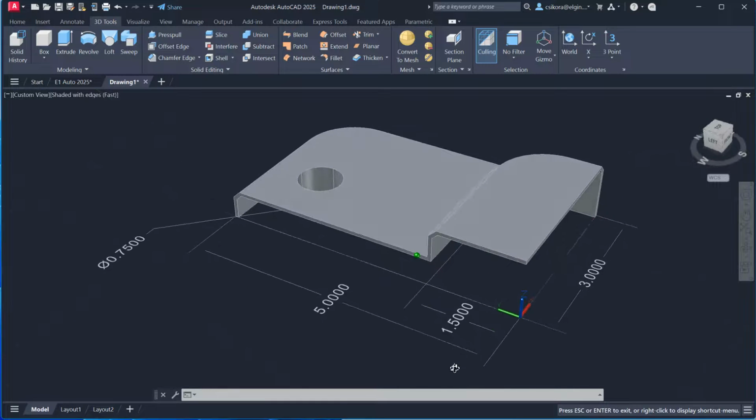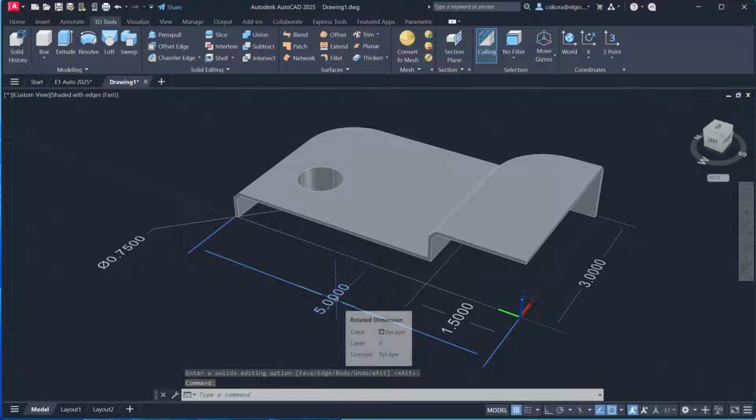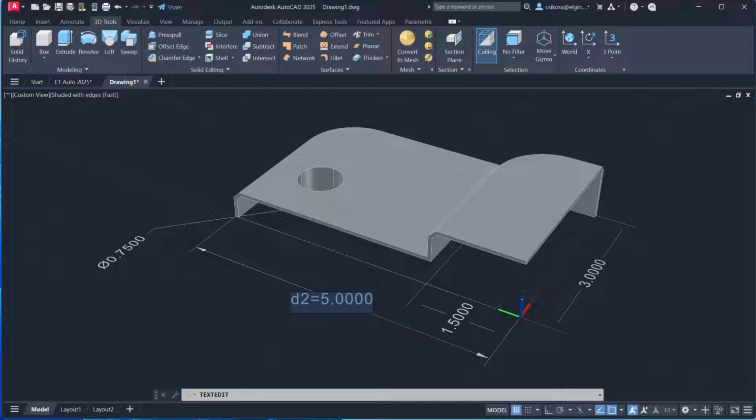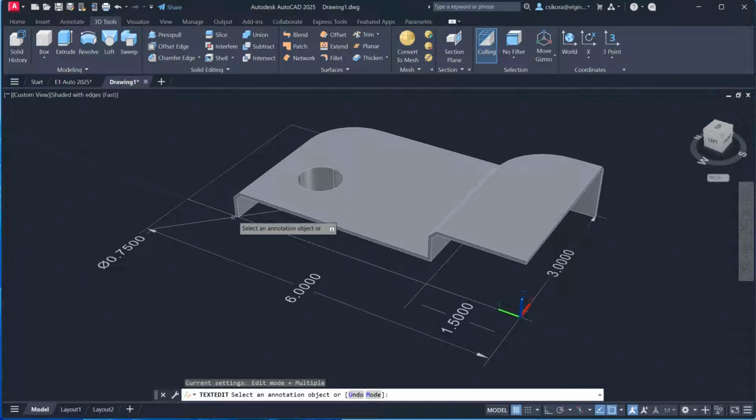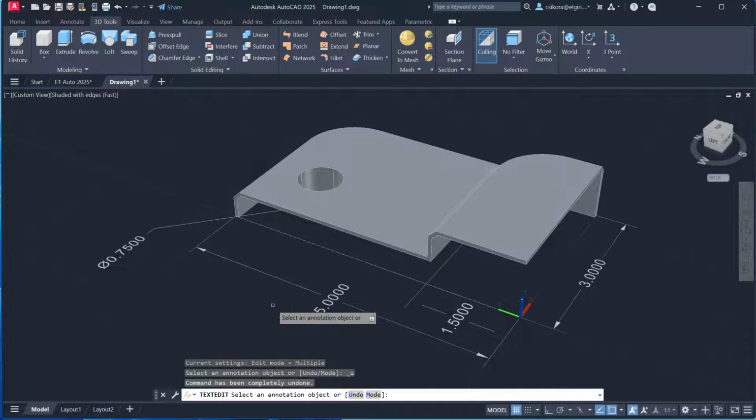Now here's the downside of the parametric sketches in the software. They have another tool called Inventor, which this would update, but if I double click on this 5 and try and change it to 6 like we saw earlier, the geometry doesn't follow. I'm going to hit Control Z, which is undo, to undo that. But you could reuse that sketch for other geometry, so it is useful to have it as parametric.